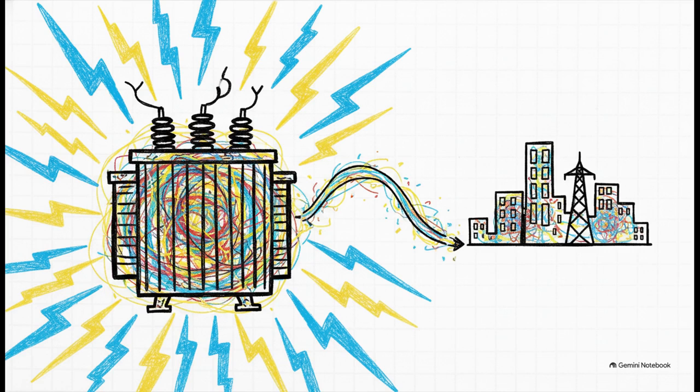If you want to calculate the exact power output where your transformer performs at its absolute best, you just take your full load kVA and multiply it by that optimal fraction we just derived, the square root of iron loss over copper loss. This formula is a real game changer for engineers. It lets them pinpoint the precise output kVA for peak efficiency, ensuring we get the maximum possible performance out of our grid without wasting precious energy.